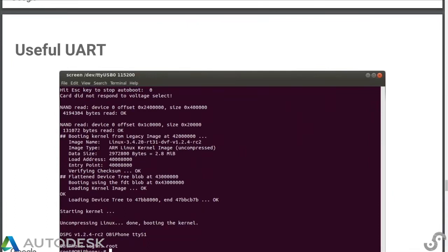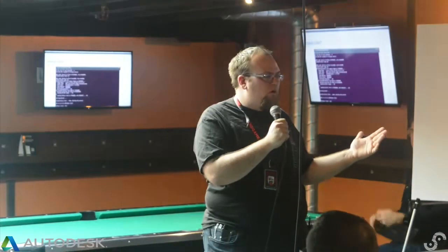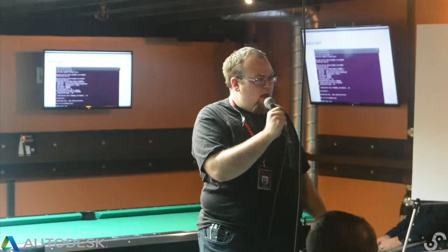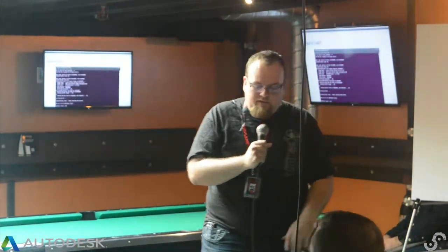I mean, this is entertaining. But in and of itself, it's not really a vulnerability because if someone has hooked up a UART to the device in your facility, you've lost at that point anyway. But it's just really amusing. Sometimes it's super easy like this because then at this point you're like, oh, I have a root shell. I can do whatever I want to investigate this device. If you get this on a device and you don't have a firmware download or something like that, you can use DD and read from the raw flash device, and you can create your own firmware image from the device. Which is super useful if you're not able to find a download firmware or something like that. The other benefit of having a shell while you're on it is you can find out what happens when you are interacting with the device.